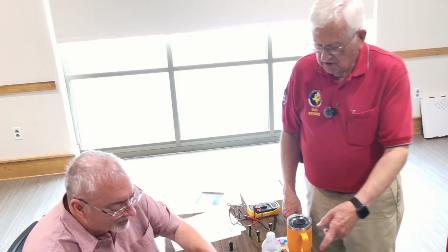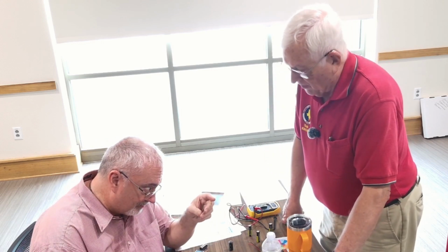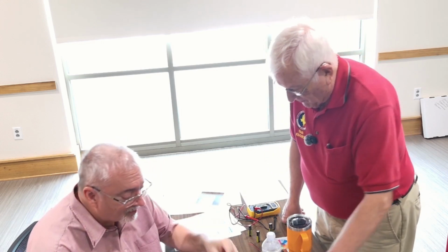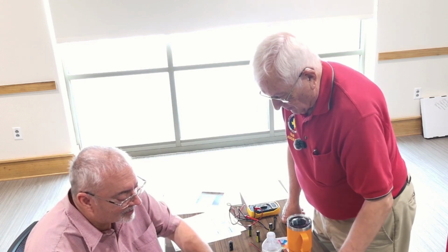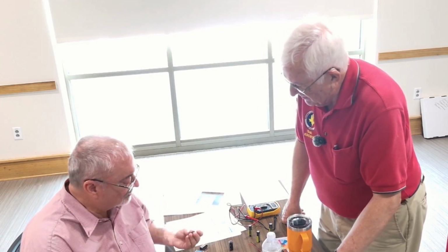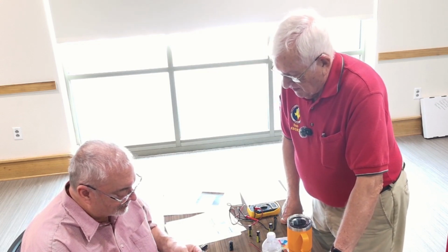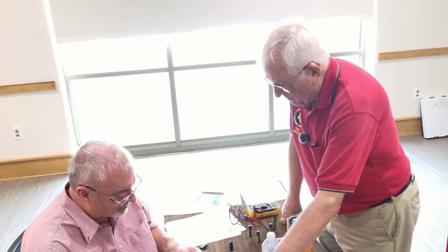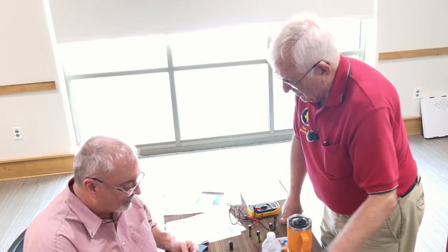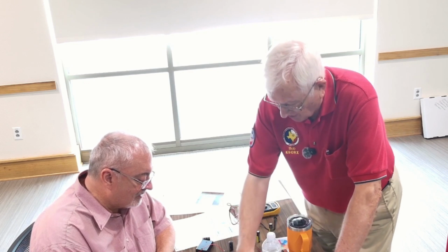And you can do the same thing with the little ones. Now, these are also polarized or no? No, those are not polarized. If you don't have a stripe down the side, they're not polarized. See, like this one is polarized. It's got a stripe. These little guys, you want to be sure when you measure those that you don't hold the leads because of your body capacitance. Now on these, it's not going to matter, but on these little guys, it will matter.